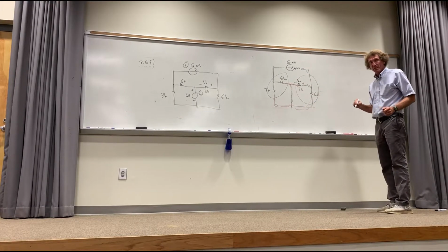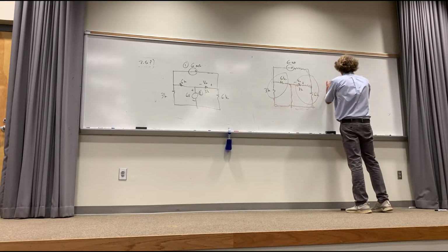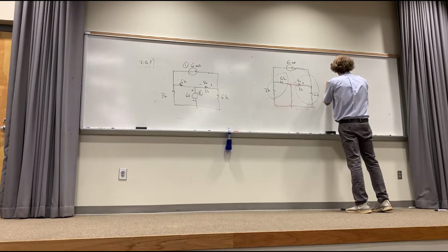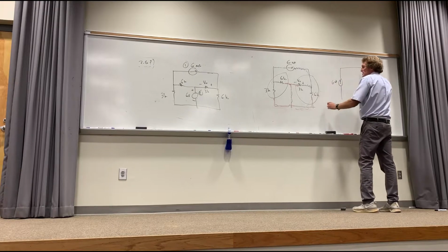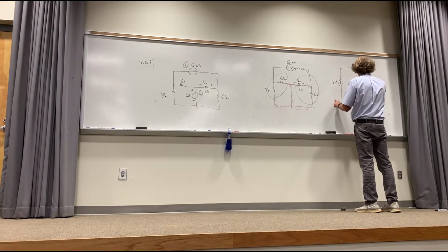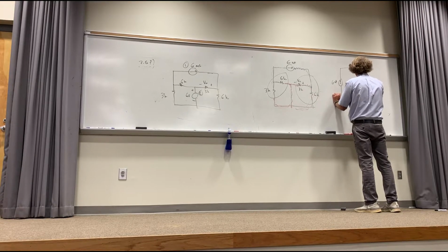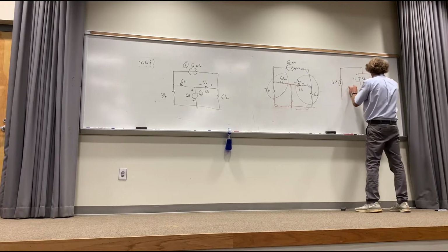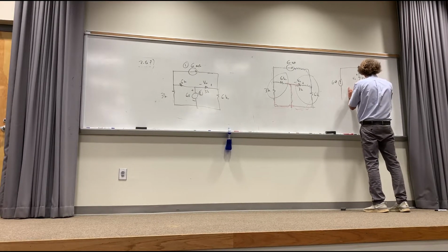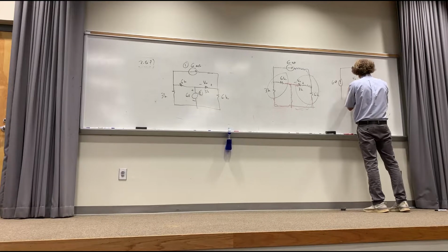Follow me, everybody? I'm gonna redraw it so you see. So now I've got my 6 milliamps and I'm gonna put that vertical. Here comes these two resistors, right? That resistor is 3K. And there's a plus to minus V naught I gotta find. It's in parallel with 6K right here.